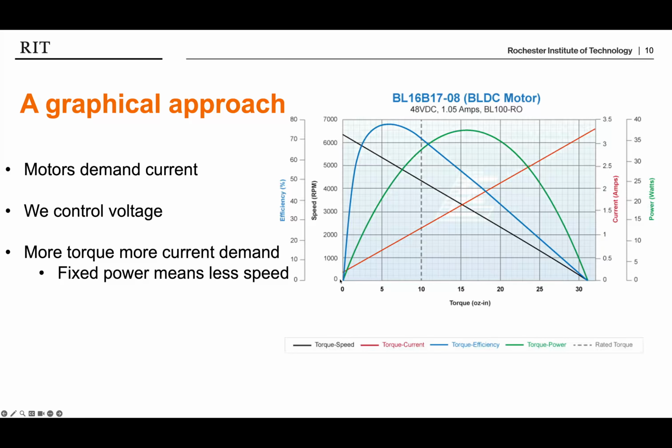And at first you go, well, that seems kind of suspicious, until you realize that, actually, yeah, I have to get a certain amount of current through my coil of wire before a magnetic field builds that's strong enough to do anything. So there's this little offset here. And again, this is not null error. This is there as a function of the physics of a motor. So I put in a little bit of current, a little bit more, and all of a sudden my motor starts rotating.